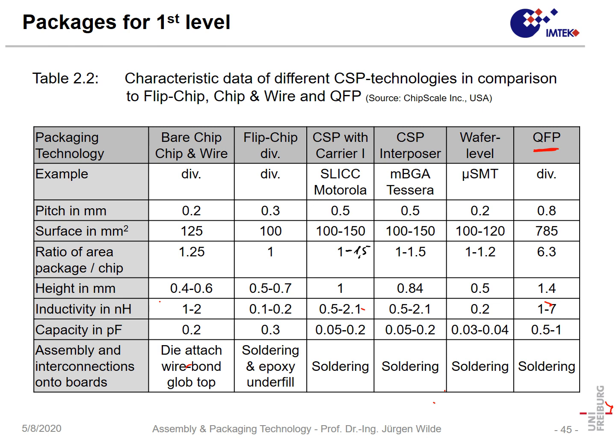So in the end, having modern package technologies for chip scale packages, the pitch we can achieve is in the order of magnitude of what we can achieve with chip and wire and with flip chip technology. In the end, people processing printed wiring boards and making second level integration prefer devices in a package.